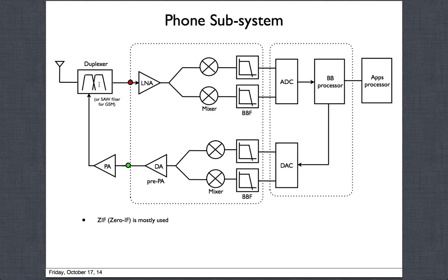There are going to be a lot of interferers there. A lot of other channels, adjacent channels, not in this band but maybe outside. And there is a mask for it, like how strong these signals could be, and those signals also could be significantly strong, and that would actually wash out the RX. So to protect that, we have this filter, so that we can filter out the out of band jammers, which is what we call them.